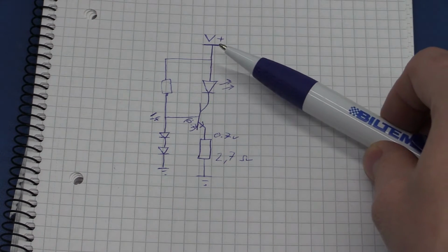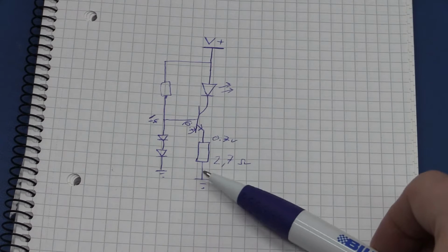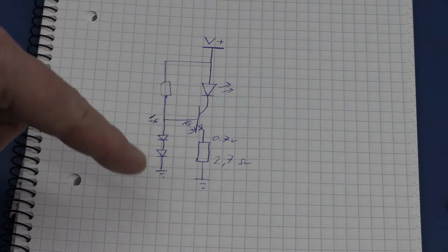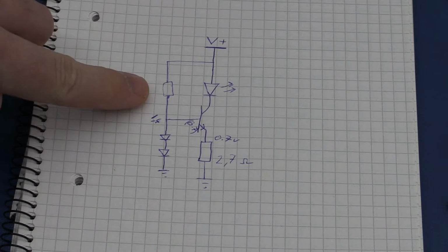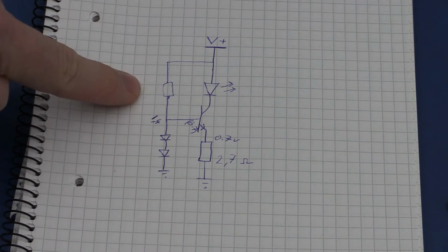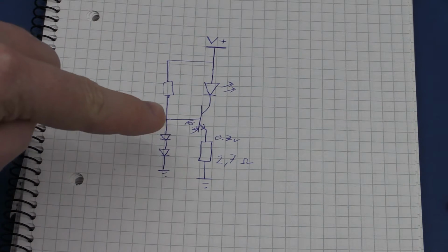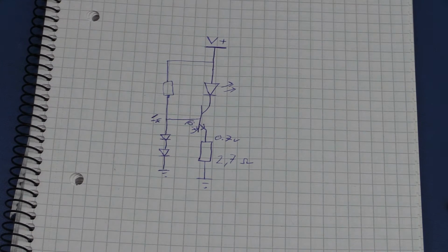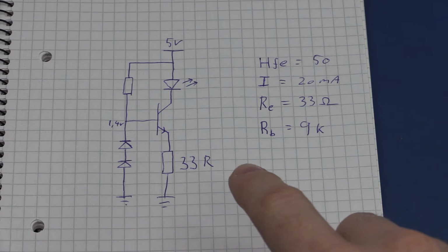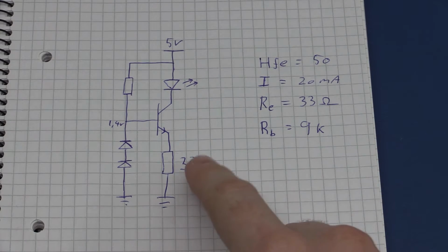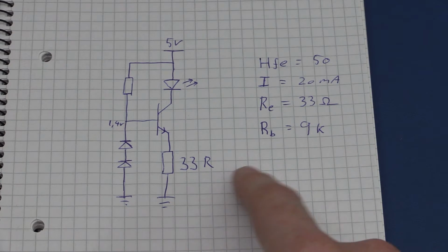But the good thing about it is if you increase the voltage, it doesn't affect the current, it just affects the power dissipation. So just a quick calculation, if we set a 5 volt supply, we would need a 692 ohm resistor here to give us the current that we want. But I want to make it with slightly less power, so I will make a new one for the 20 milliamp diode. I just did the same calculations again, and it turns out for 20 milliamps we need, I think it was a 35 ohm resistor. I just rounded down to 33 ohms.